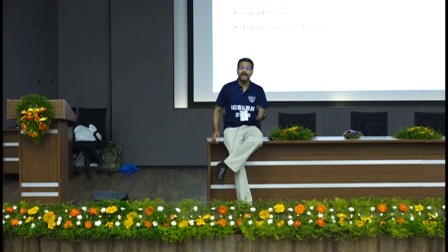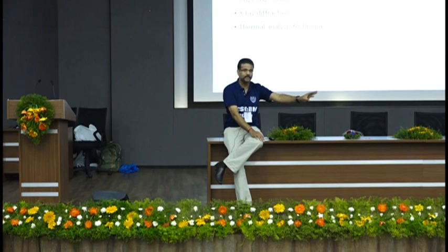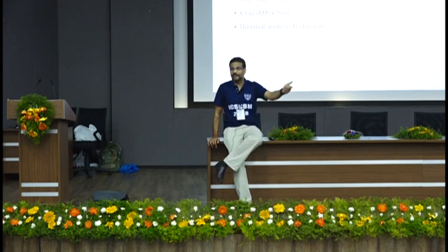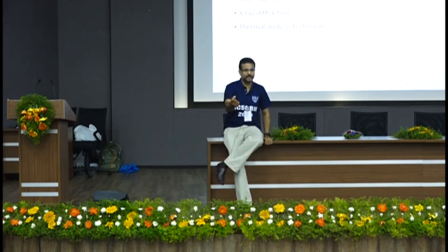Displace as much as you can, and that is again the point that you have to have a comparison system and say that compared to an OPC paste, my paste with 20% fly ash shows me X% lower porosity and X% lower pore size. Now you're totally fine because you're comparing with a known standard. It's a relative measure. I know my OPC has larger pores, but putting fly ash or silica fume has lowered my pore sizes, and I know from common sense that lowering pore sizes will slow down transport, therefore make my concrete more durable.